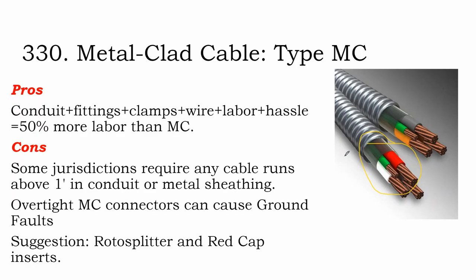With multiple conductor cables, you're not pulling through anything. They already are kind of done for you. Whereas otherwise, if you're using single conductors and conduit, you build your conduit run and you pull your single conductors through it. So the question is, when do you use a pre-made cable and when do you not? In general construction, using a pre-made cable, if you can get away with it, might cost a little bit more in material, but you make it up with labor.